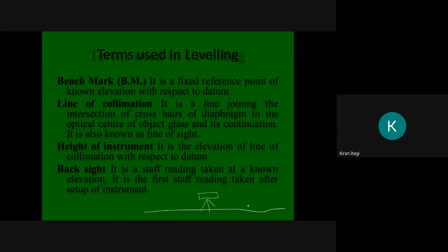Here I have stations A, B, C, and here I have my benchmark, 100. Before I proceed forward, first I should take the reading with respect to my benchmark.